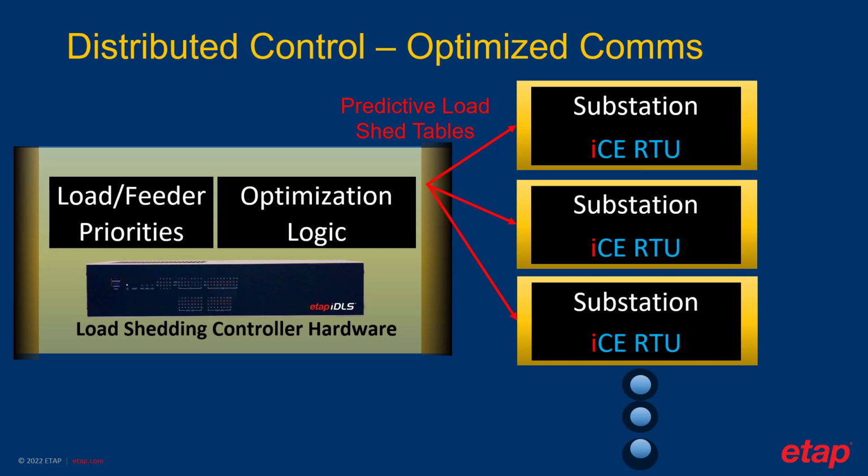At this point, the controller is armed with the necessary loads to shed in the event a contingency is true. Now, in the event where a contingency trigger is true, this can be because either the controller determines that load shedding is necessary or the operator needs to drop load from the network in order to keep the system stable. Each one of the controllers at the substation level will issue commands to trip loads locally, therefore ensuring that we have fast response over a large distributed control network.